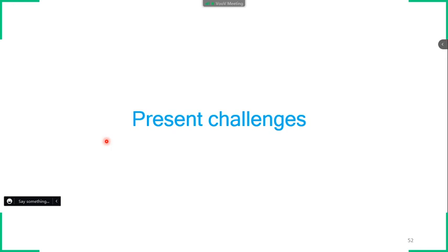It will generate a distortion, but if your plate is sufficiently thick, then why worry about distortion? That is what I'm saying. You have to go for a thick plate like 15 mm or 20 mm. If you are taking that, then why do you need to worry about the distortion? Definitely it won't get distorted. And maintain interpass layer temperature, so of course it won't get distorted. And if you are depositing continuously, a lot of heat stagnation will take place, then it may get distorted.